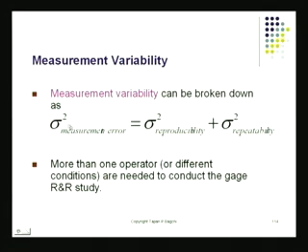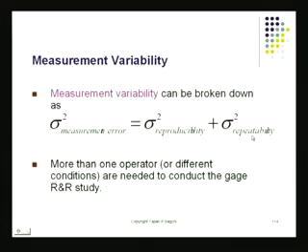So measurement errors could be caused by people or by instruments. If different technicians are producing different readings, the measurement system has a reproducibility problem. And if the same instrument produces different readings in the hands of the same individual, then there is a repeatability problem. These again have to be understood, and you have to make sure that the total measurement error is quite low. Normally speaking, in industry people say measurement error should not be more than 10% of what you are trying to measure.